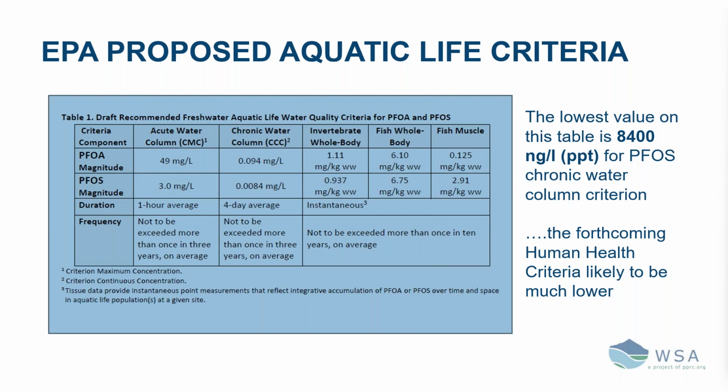But the implication for any size wastewater treatment plant, particularly the large ones, is that if they're discharging into a water quality segment that's covered under a water quality standard, then the discharge permit can be amended to include either sampling and monitoring for these pollutants and reporting the values that you get, or in some cases, and that's already happening in some states, actual limits. It's a requirement, and so their sampling and testing has to be at or below the limits that are in the discharge permit.